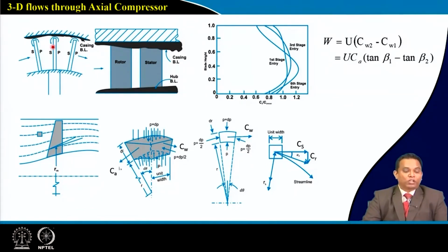Now we have also understood, in order to have free rotation of our wheel, we need to provide a certain amount of clearance between casing and our blade. Now this is one of the areas of research for many. Here if you look at, on my pressure side we will have, say, higher pressure, on our suction side we will have lower pressure, and we can understand our rotation of wheel is from suction side to the pressure side.